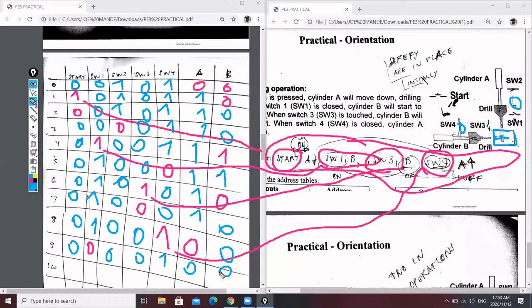And then on step 10, it says cylinder A is back. It means this weight, which was maybe in the middle, is now on top there, so switch 2 will become closed. The only change is that this switch is on top, so whatever name we give it, it will be closed. Then every time a closed switch happens, we must check in the logic order. When you check in the logic order, there is no switch 2, which means nothing will change.